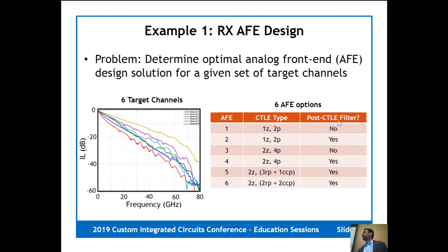The reason is that most of this crosstalk is coming, at least in the LR case, from the connectors and the backplane. So there are things you can do in the connectors. On the SerDes side itself, people are paying much more attention to how they break out these signals from the boards in order to minimize the crosstalk, the IC and the package itself. And outside that, it's in the connector, and modifications in that connector to minimize the crosstalk. So the approach has mostly been to look at ways to control crosstalk rather than accommodate it and cancel it.